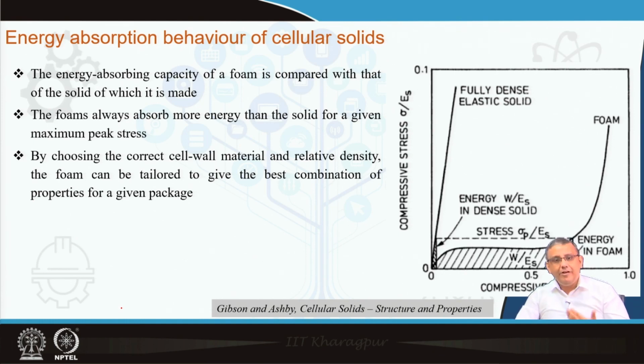However, when we go for energy absorption or other applications, it is the compressive behavior of the foams that matters, because under compression the pores are compressed and collapse upon each other, and that gives rise to a very high amount of deformation, depending upon the type of material being used.